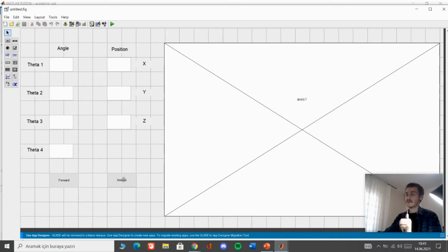This time, an inverse kinematic function is applied to the robot manipulator and the desired theta angles to reach this position entered by the user are calculated by using an inverse kinematic function, and the resultant theta angles are shown here. Also, the motion of the robot and trajectory path of the robot can be observed at this portion of the screen.